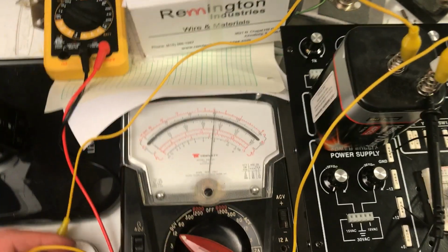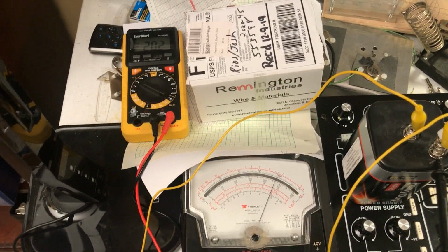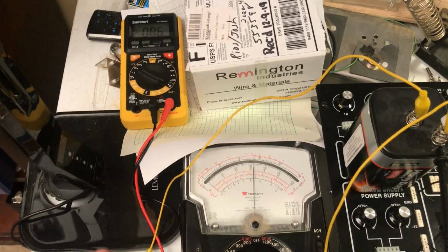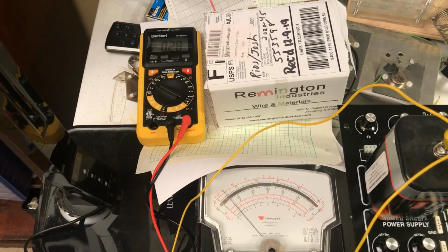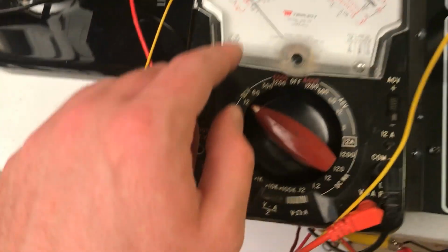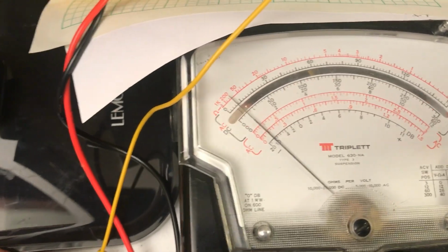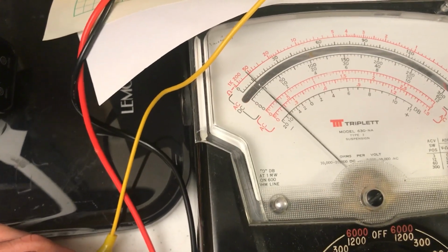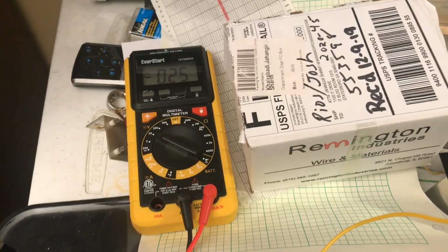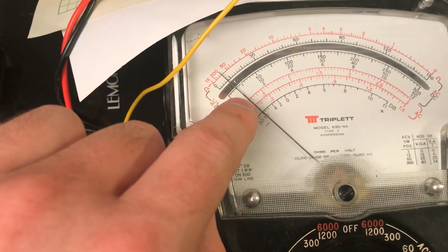It amplifies direct currents. Now, as you see, when you change the input up or down, there's actually a delay caused by the rectifier cap trying to discharge to the right value. Well, 0.2 would give us 1 volt, wouldn't it? 0.19. And you can see we wait and it moves, and when it stops moving is when it's equilibrated. Okay, this is 0.25, which would give us 1.25. Close enough. It's almost 1 volt. And it's not quite accurate, but it works.